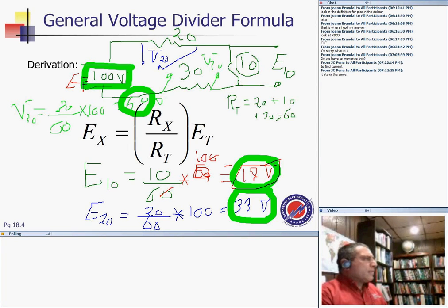So then, what is the voltage divider formula? The voltage divider formula is another way of finding the voltage across resistors in series. That's all. The biggest resistor will get the largest amount of voltage, and the smaller resistors will get a smaller amount.